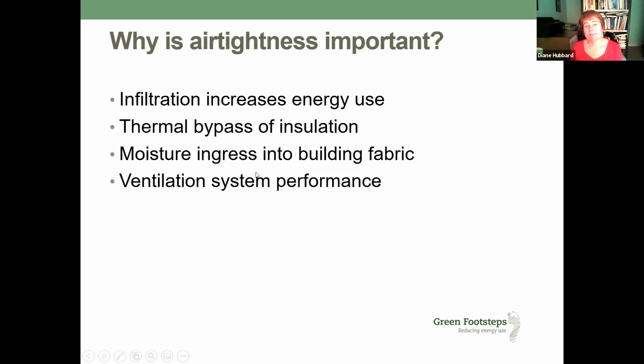So why is air tightness important? Well, if we've got all this unwanted air moving around in the building, then we're basically increasing energy use. Now, the thing about air is it actually takes relatively little energy to heat air compared to other materials like water or concrete or brick. But it does increase the energy use.